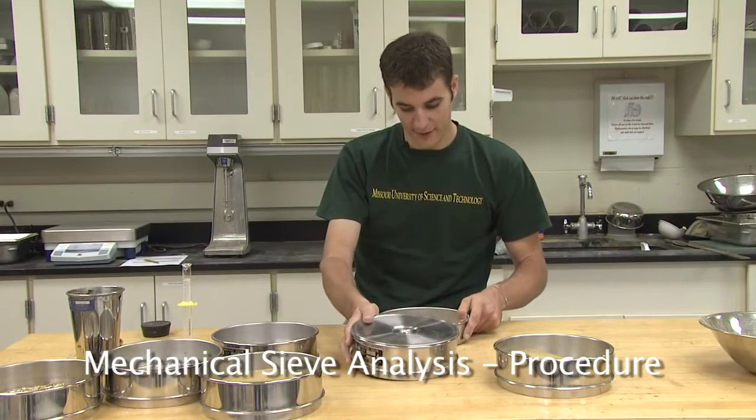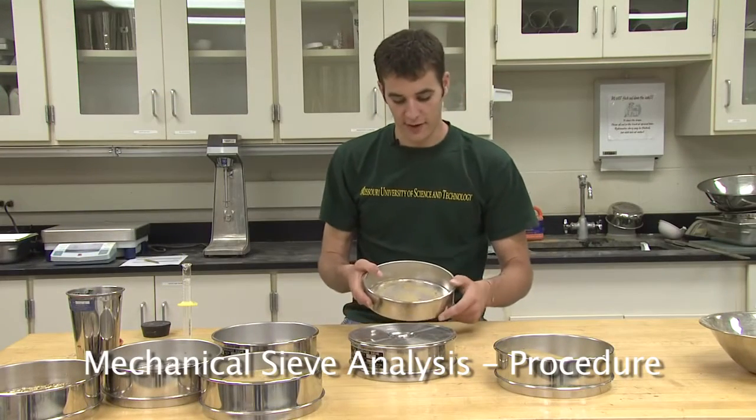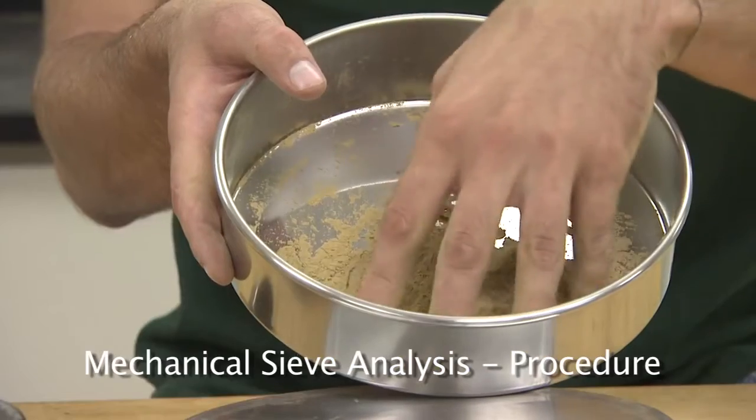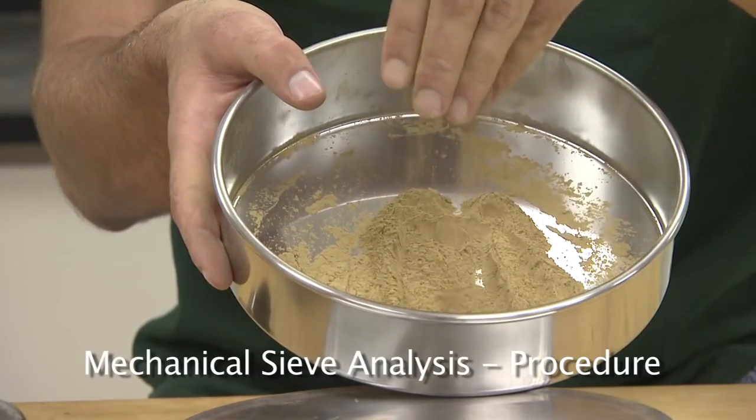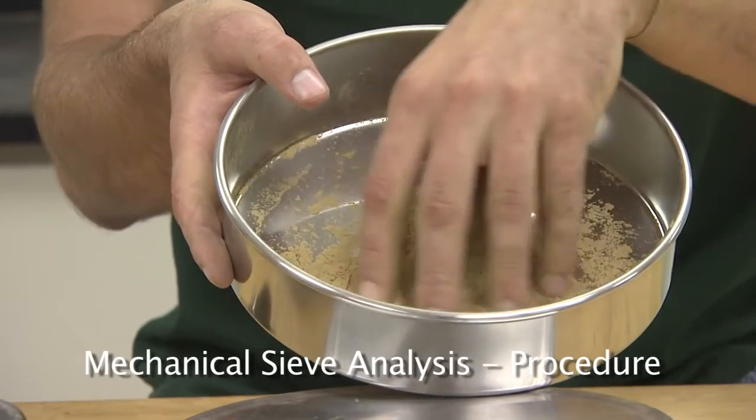Empty the material in the pan in a bowl and record the weight. This material is the material that has passed the number 200 sieve. It is considered the fine-grained portion of this material. This material will be used in the hydrometer analysis portion of this lab.